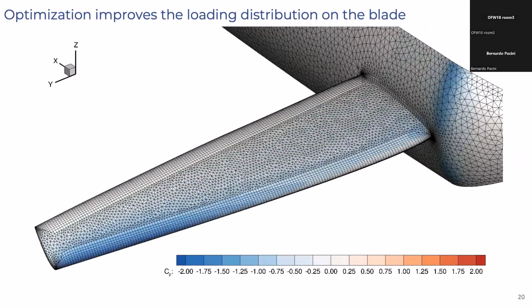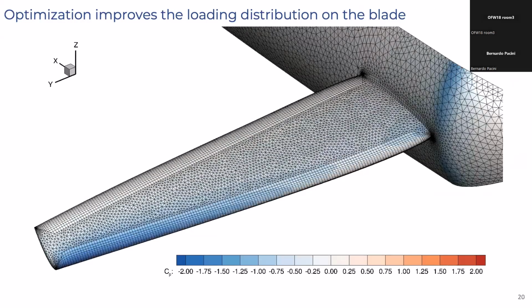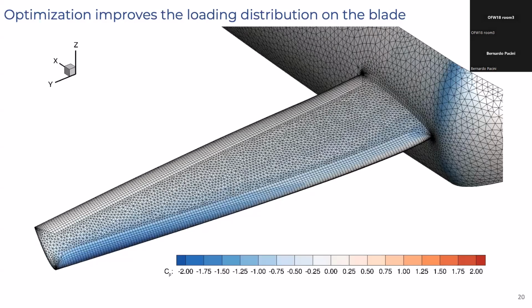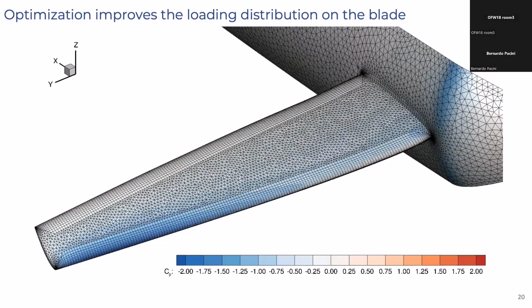Both of these we can use with different flight conditions. So our codes can be multi-point. So we can set up two separate geometries. Even if you have variable pitch, you can vary RPM, however you'd like to set it up. And then you can weigh the objective for both of them. We could do it both for this case and the blade element momentum theory case.